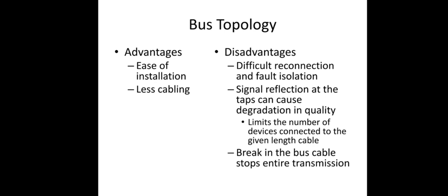And coming to the main advantages of this method, ease of installation, right? Any devices can be directly plugged into this backbone cable using these taps and drop lines. So that's the main advantage. And also less cabling is required, right? Only one backbone cable and drop lines are required.